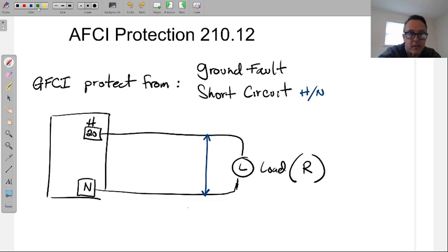Now, what really happens in a short circuit? Well, resistance goes away. You lose R. That's the feature that happened in the short circuit. So technically, the short circuit can happen here at the load, where the hot and the neutral touch. It can happen down here at the junction box. Somebody could have cut our Romex leaving the panel, who knows where the short circuit happens. But that's what a short circuit is, when the hot and the neutral come into contact with each other. A massive amount of amperage goes into this circuit, but we don't have to get into the calculations.